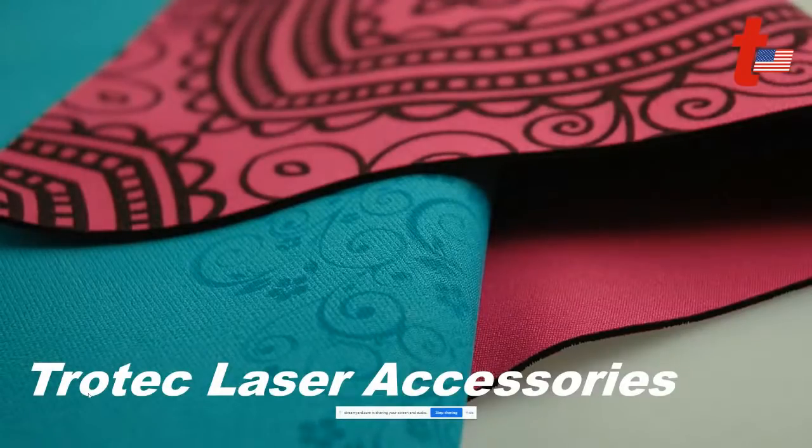But for small engraving areas, it is recommended to do the engraving process, because as you can see there, it can be heat transferred onto the surface of the material. So if you're doing small text areas, detailed areas, labeling, where you want to get that intricate detail, but you don't want to sit there and pick out all the excess material, you can use the laser system to do that. As you saw on the video, the recommended solution for that is to use a tacky mat.